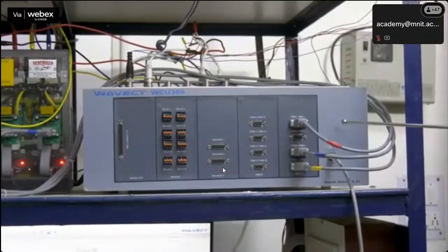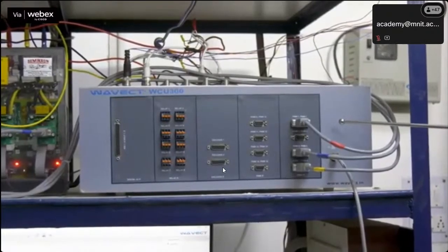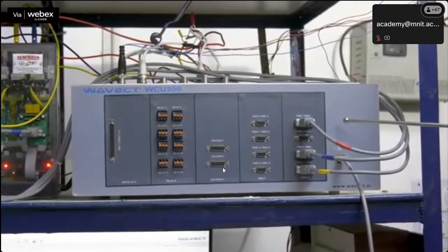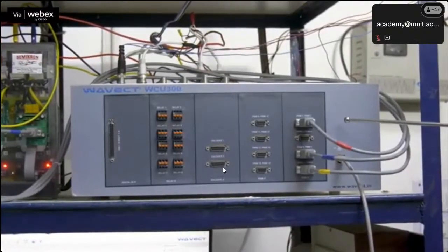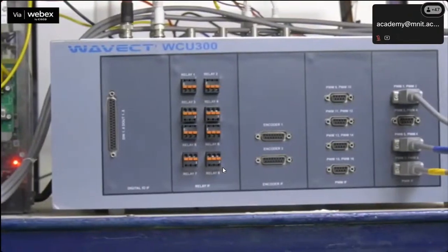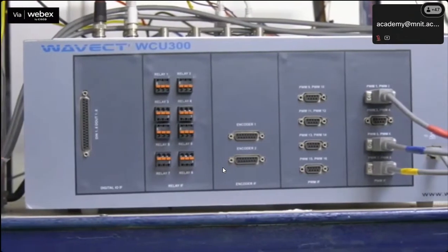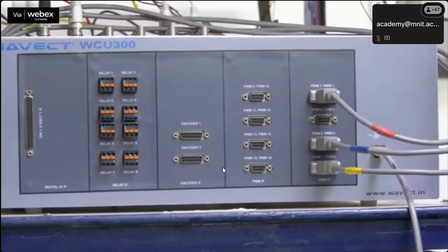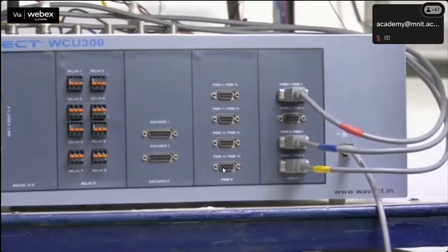We are using an FPGA powered Xilinx Zynq SoC XC7Z020 controller to perform our control strategy. The controller is equipped with integrated voltage and current sensors that can directly measure up to plus or minus 1000 volts and 25 ampere with internally isolated channels.